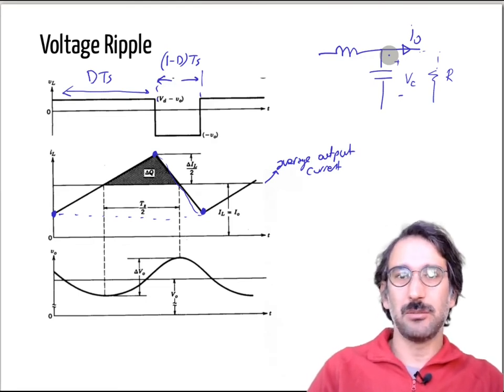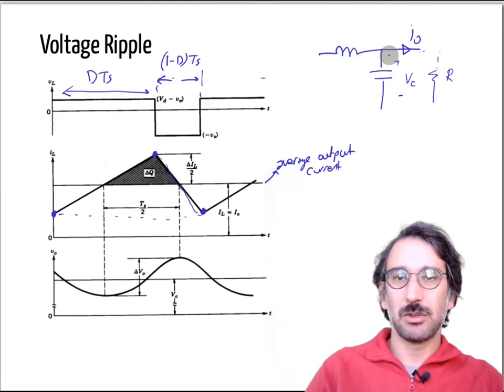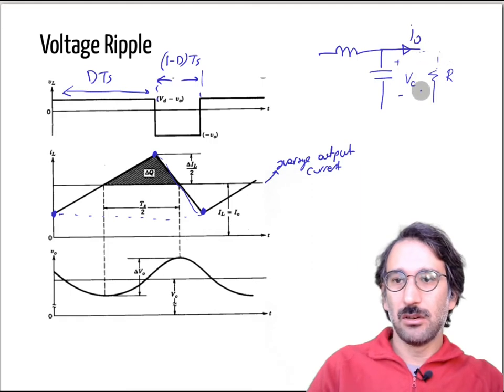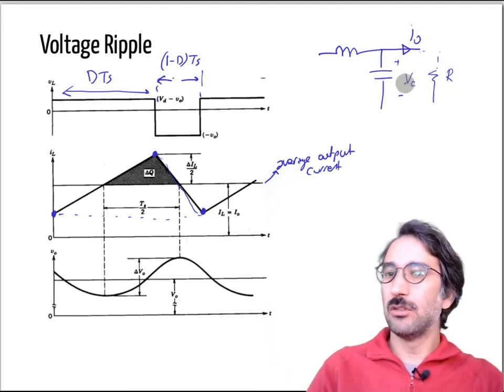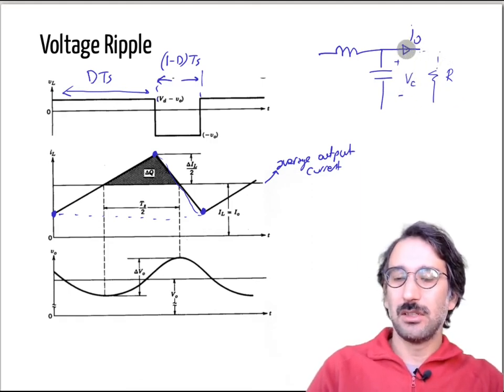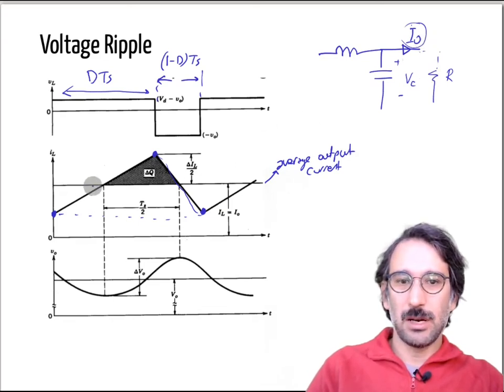Of course it can be solved, and you can see those effects in your computer simulations. But for us, let's assume that ripple is small, so for current we don't take that effect into account, and we can assume that the current going through that resistance is more or less DC.